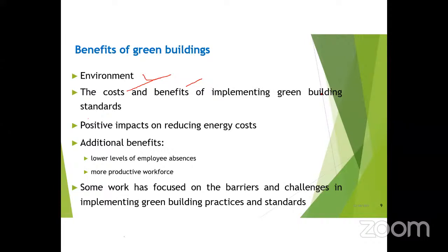So this is done. We are going to use low flow fixtures and dual plumbing systems, you know, a single plumbing system and dual, one pipe system, 2 pipe system. For the 2 pipe system, we are giving 2 pipes for the gray water as well as black water. That is the 2 water system. So we are using the 2 pipe system or dual plumbing system in the green building. So we can segregate and collect our gray water, and that can be recycled and reused.